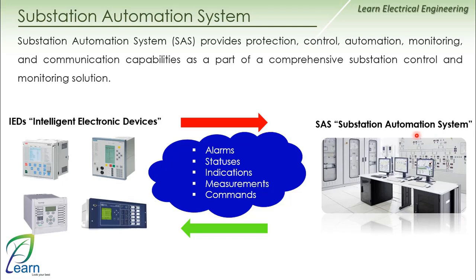Of course. Now, regarding the substation automation system, it is an alternative to the control panels. What did I say? I said I would save the space that I would use for installing the control panels, save the cost of the control panels with the components inside them, and save on the cables extending between the GIS building and the control panels.